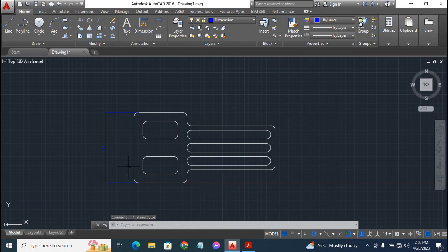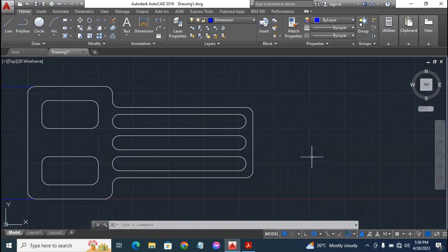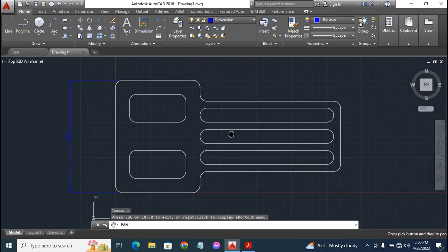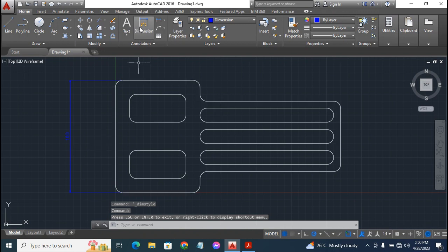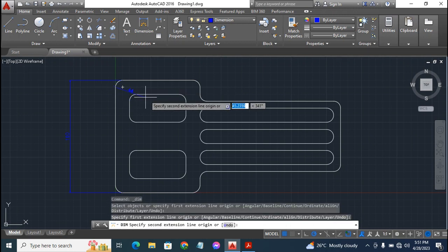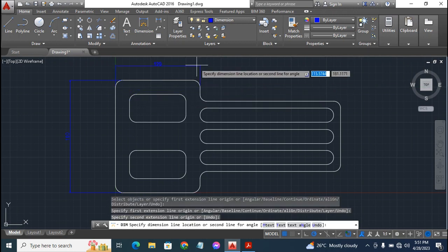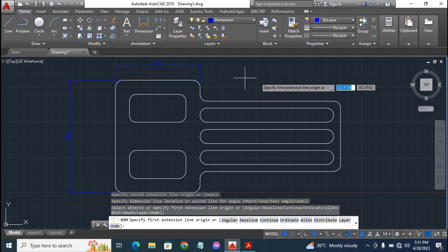As you can see, these changes have really come into effect on our drawing, but it's still not very visible. So I'm zooming out so that you can see what I'm doing. Press escape key. To input other dimensions, go to dimension, click on dimension, click on both ends of the line you want to dimension, and drag upwards to take it away from your major drawing.